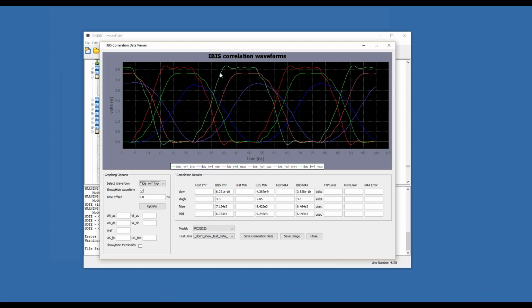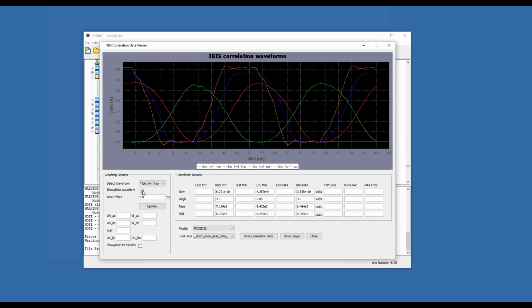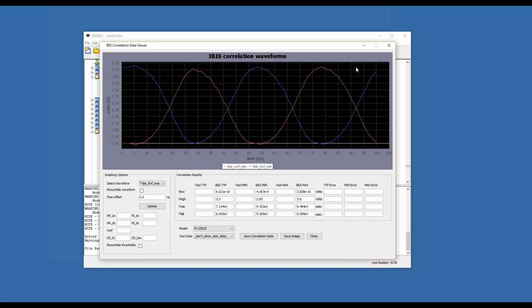So you can see that because we have a fairly long transmission line, a nanosecond, which would be a couple of inches, right? The max corner does, maybe some termination would be good in this case, but it seems like it's driving enough. Typ is slowing down. It's slow. You're really starting to push the boundaries of this driver in this case. You're almost getting this sinusoidal waveform here.